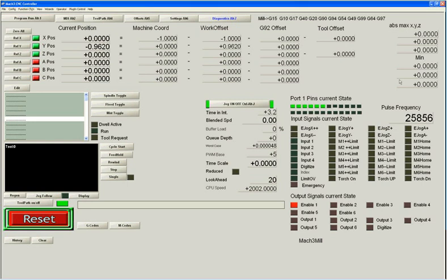Another common problem that people have is they say, my printer port just doesn't seem to be working. It's not putting anything out. Well, sometimes charge pumps and things like that can make a breakout board not accept motor output signals. So let's take a quick look at how you can check your printer port to make sure it's working.